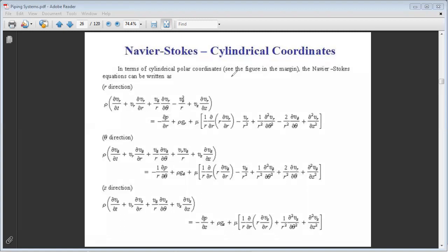Okay, so where was I, when did the sound start cutting? So we are studying a flow in a duct, and we are studying the fully developed case, meaning the velocity is only along Z. It's only a function of R because it is fully developed and steady, with no change along the axial direction, so any cross section keeps the same profile. Concerning theta, because there is axis symmetry, V is independent of theta: for the same R, whatever theta is, the velocity stays the same. The velocity changes with the radius, being maximum at the center line and zero at the wall due to the no-slip condition, if the tube is fixed.